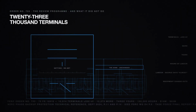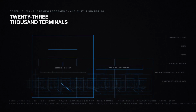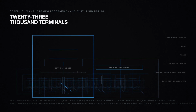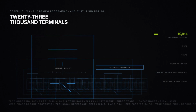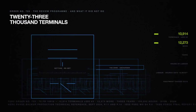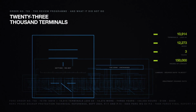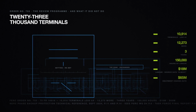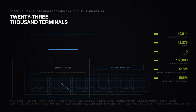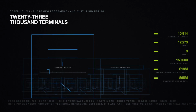10,914 relay terminals at 200 kilovolts and above were examined, and then 12,273 more. That is the post-blackout review program as the federal regulator records it. Over 3 years, 150,000 hours of labor, almost $18 million, and 65 million of equipment changeouts. What all that work did was change settings. It did not remove the element.